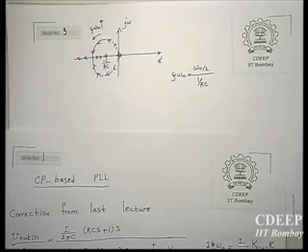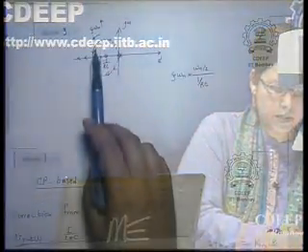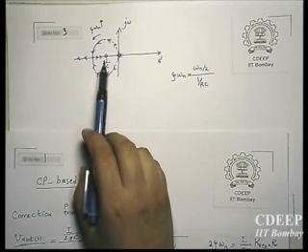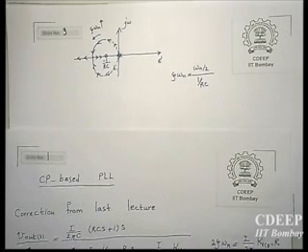Suppose, for example, you keep omega n constant. This means that you need to reduce 1 upon RC. That means that as you are increasing zeta omega n, 1 upon RC all shifts to the right, which is the limit when your zeta is infinite. So though you are trying to stabilize the system, at the same time you are reducing the bandwidth, which is good, of course, with respect to jitter and noise performance, but it is not good with respect to latency of the loop.